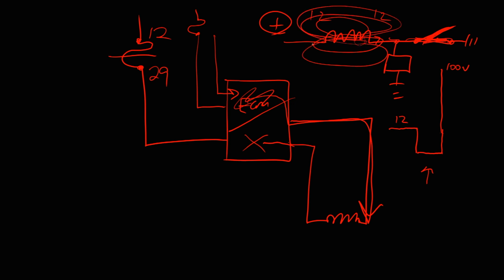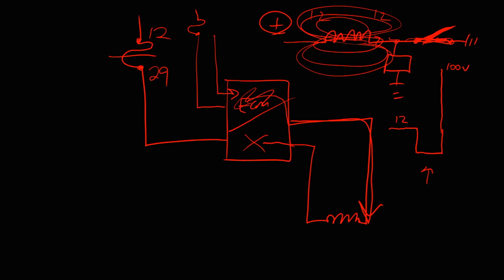What is that? It's a magnetic field. So what happens when we open the switch? What happens to that magnetic field? It collapses. It's a voltage spike. That's the collapse of a magnetic field. Then from that point, it now returns back to 12 volts.